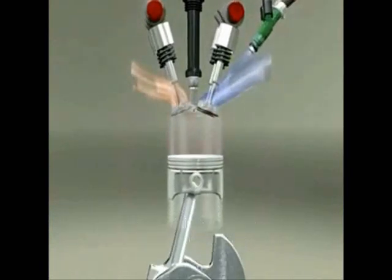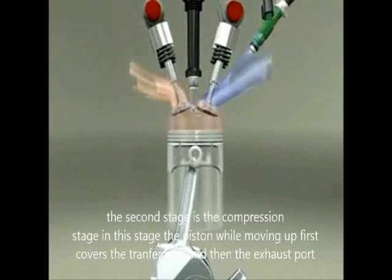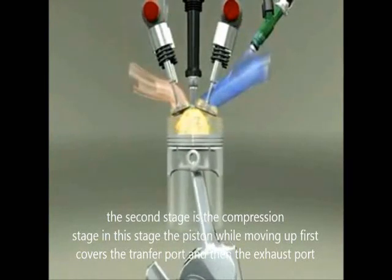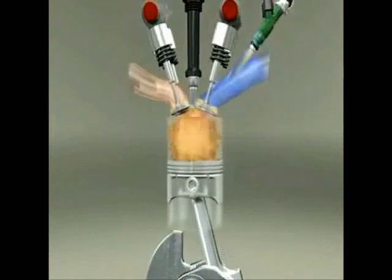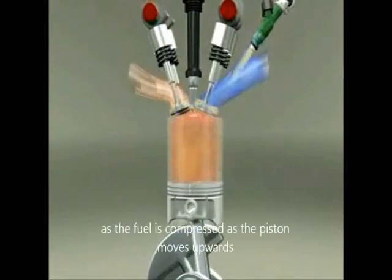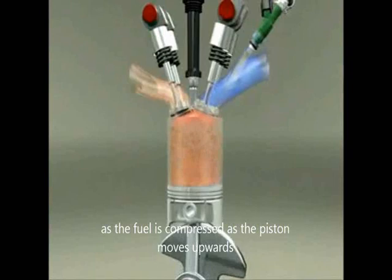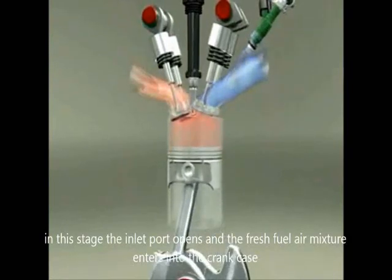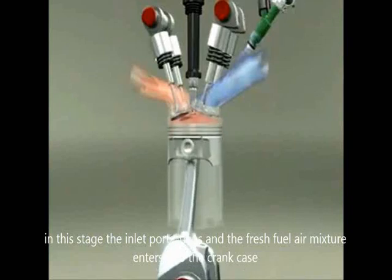The second stage is the compression stage. In this stage, the piston, while moving up, first covers the transfer port and then the exhaust port. The fuel is compressed as the piston moves upwards. In this stage, the inlet port opens and the fresh fuel-air mixture enters into the crankcase.